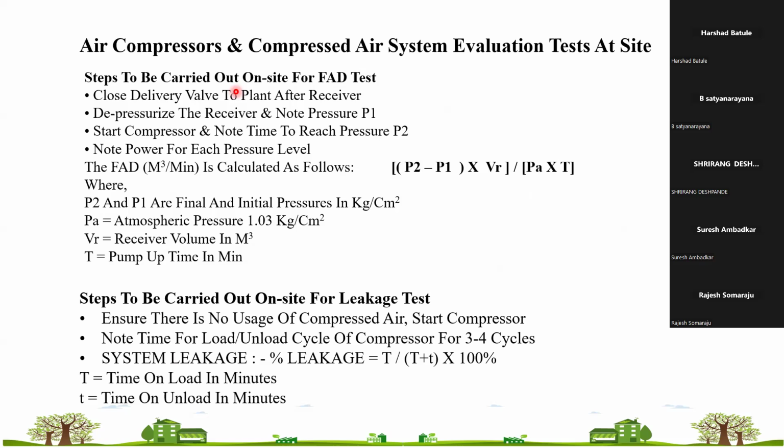During the free air delivery test, what is the formula for calculating the free air delivery? It is P2 minus P1, divided by PA, the ambient pressure, into the volume of the receiver, divided by the time to fill. I'll explain this one by one, the procedure to calculate the free air delivery. Suppose you have this system.